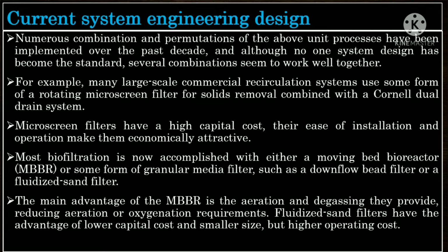Cornell dual drain system. Although the microscreen filters have a higher capital cost, their ease of installation and operation make them economically attractive. Most biofiltration is now accomplished with either a moving bed bioreactor, or MBBR, or some form of granular media filter, such as the downflow bed filter or the fluidized sand filter.